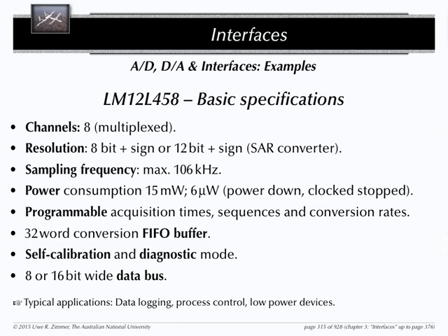You can tell this device, for example, trigger an interrupt for me when you have done so and so many conversions, so that I can start catching up as the CPU, and then the CPU reads it out of the buffer quite quickly. You can empty this buffer a lot faster than the AD converter can fill it from the other side.